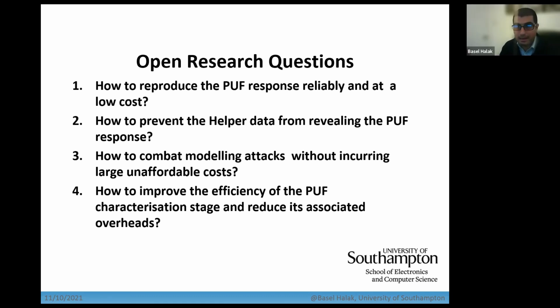That's the problem. At the heart of it, a PUF is simply an integrated circuit. There is some dependency between input and output, and that can be captured by a machine learning algorithm. If you increase the complexity of the design, all you're doing is increasing the time needed to build the model. With the latest deep learning approaches, there is no PUF that can actually withstand this type of attack. But the good news is that we don't always have to worry about it, because it might simply be infeasible practically. You can't wait a long time to collect these challenges and responses. So there are ways around it, maybe at the protocol level. But if you are talking about a white box adversary that has access to the underlying PUF, then that's quite hard to protect against.